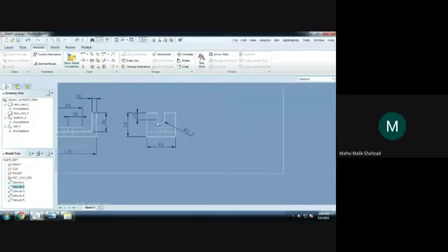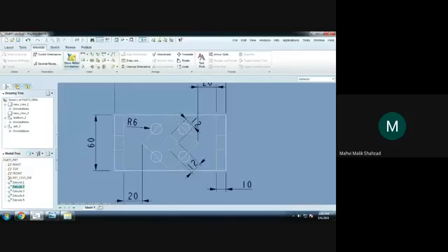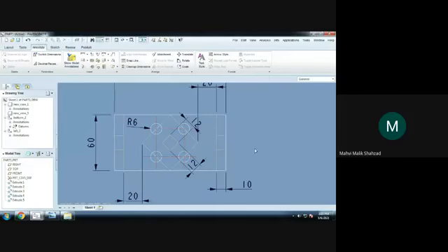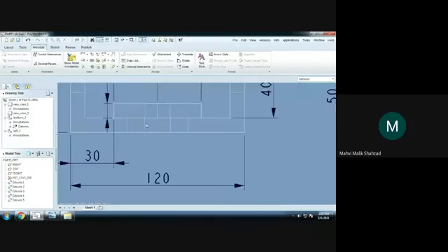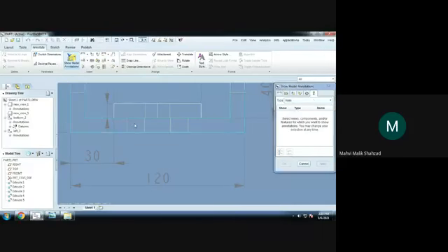So we can draw it. Suppose it's a circle, then axis will be shown here, show model. Again go to axis, select this circle, then automatically the axis will be shown. Just select this axis, so axis will be visible. Is it okay? In the front view also we can show the axis. Just select that cylindrical area. This one is your circle, so axis is shown here.